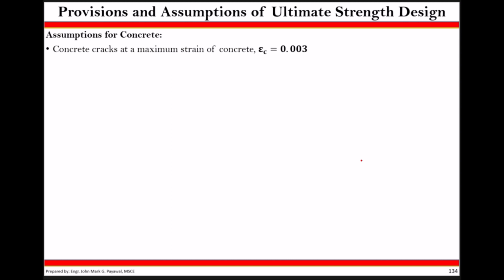In USD, what matters for me is knowing the transformed section, knowing your stress block diagram, and knowing your strain diagram. Pag ganon, kahit hindi na tayo mag-memorize ng formula, we can derive it on our own.